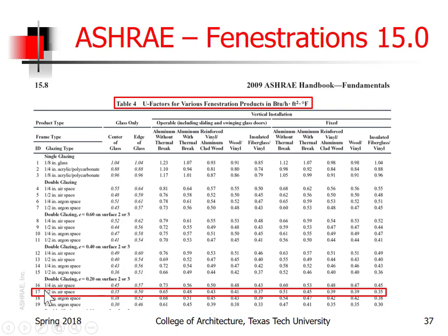And then the next thing we're going to choose, once we say, okay, we want to use double glazing with an E of 0.2 on surface 2 or 3, then the next thing is to choose what's the airspace. You'll see a 1/4 inch airspace or a 1/2 inch airspace, and then you'll see another 1/4 and a 1/2 inch with argon gas.